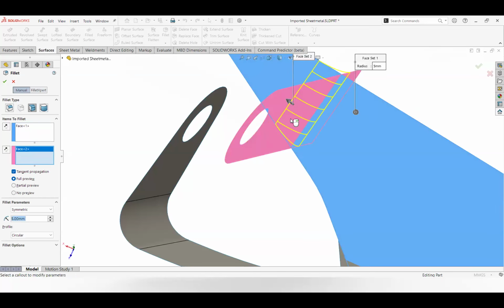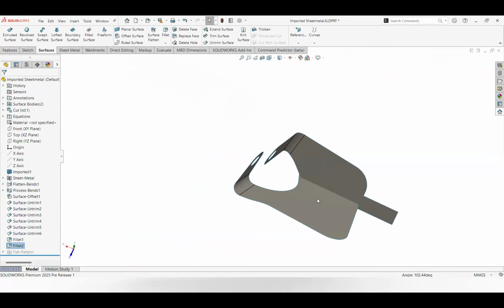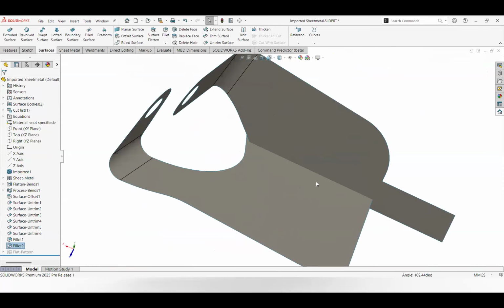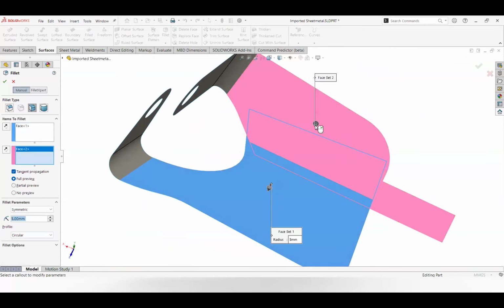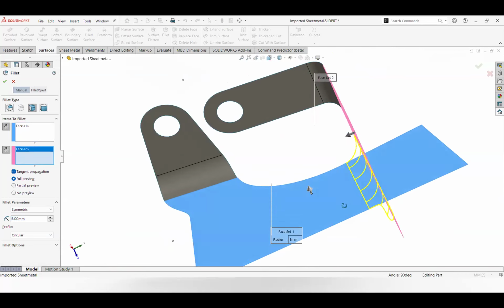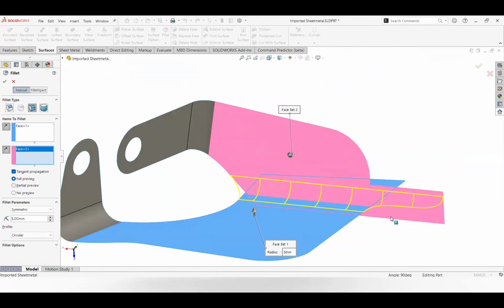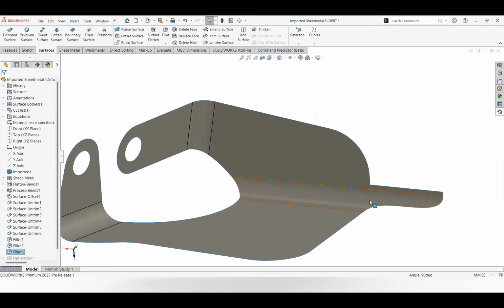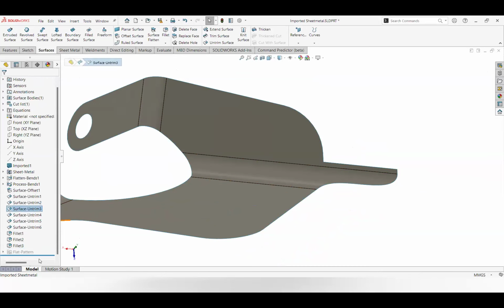And if you see me do anything that makes you think, wait, what did you do there? Let me know. I'm clicking through some of these options quickly. The trim extra, because it's a fillet, just like a fillet on a solid body, takes care of the surrounding geometry, as long as you see the preview direction. That's why in this case I've got to make sure it's going in the right way. Ooh, I'm going to get something weird there, actually. I didn't even notice that when I untrimmed this surface. I'm not going to get what I want. So let's go back to that untrim. Which one was it? I don't remember.